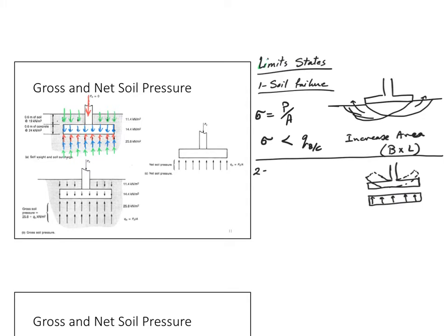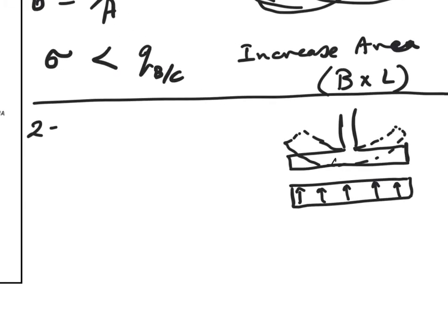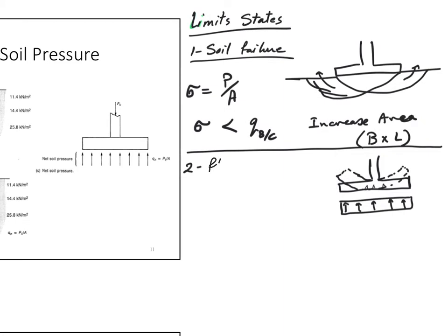So that stress pushing up, I will say that since it's a cantilever, I'm breaking this guy in flexural, right? Once it breaks in flexural, this is a flexural failure, bending, and your tension is at the bottom of the footing. So this is called the flexural limit state, flexural failure. Okay?